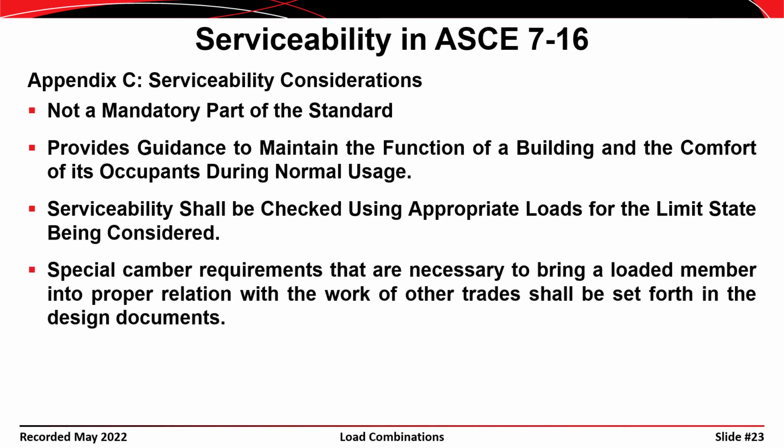It does go on and say that camber is necessary. So what camber is, basically, is where you take a beam and you bend it upwards before any loads are applied, so that when the dead loads are applied to it, it deflects into a flat or horizontal orientation. So the idea would be if you took a perfectly straight beam, let's say made out of steel, just for sake of conversation, and you suspended it between two columns, it would sag a little bit under its own weight. And then you add the weight of the concrete for the deck and for the other loads, that beam would actually sag possibly by as much as 1 inch or 2 inches in the middle, depending on the span and the stiffness of the beam and things of that nature.